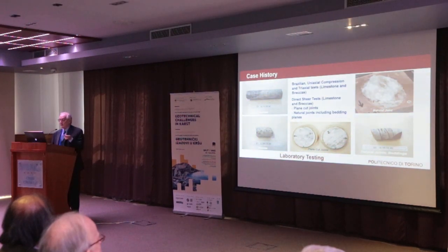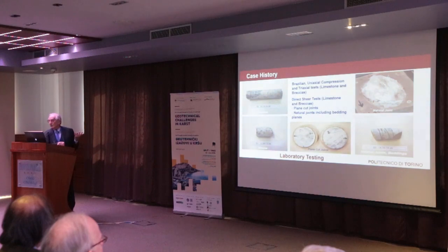I look at the joints. I look at the plane cut joints. I look at the natural joint. And I do direct shear testing. We did this with a nice looking piece of equipment that we have been able to show